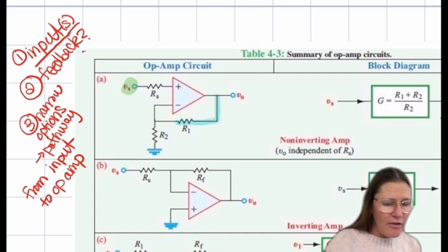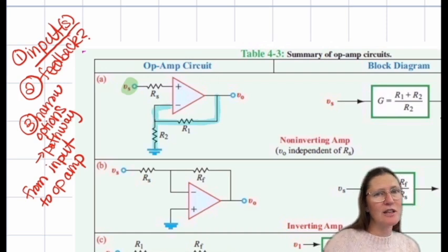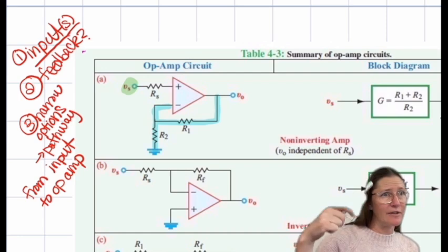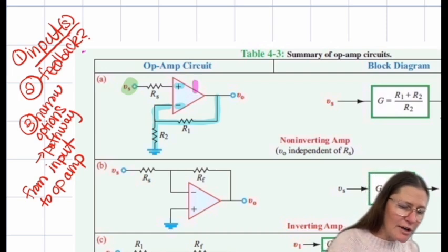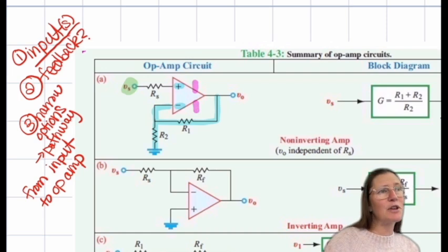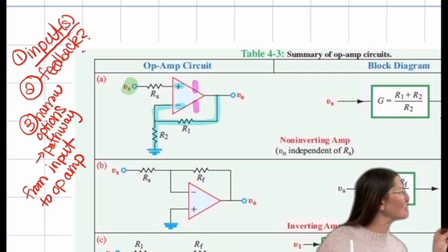That means, is there a pathway from the output back to one of the inputs, the plus or minus side. If I have little wires here and I have feedback going to them, that's not considered feedback. That's into the sources, so it is not part of the feedback. I know in some of those more complicated circuits, some of you were getting confused by that part.